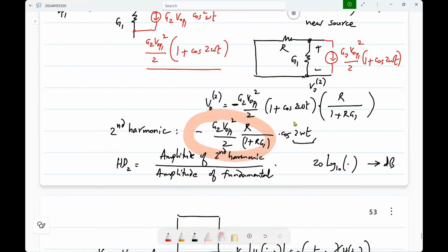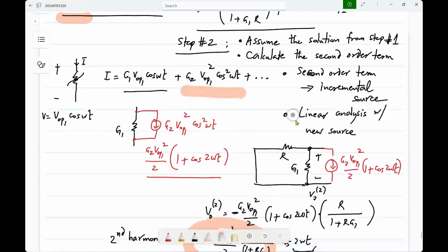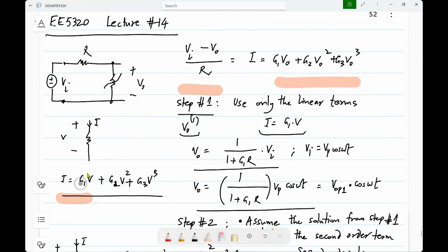That amplitude is also not correct, right? If you go through the further steps, you will get further refinement of that amplitude. Similarly for 3 omega and so on, okay? But the thing is, at least in what are called weakly nonlinear circuits, this term is more significant, this is less significant, and so on. So if the nonlinear terms are less significant than the linear term, these progressive corrections will also be successively smaller, okay? So qualitatively, we may still be okay, right?